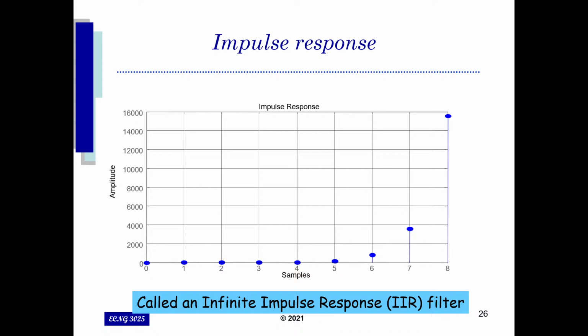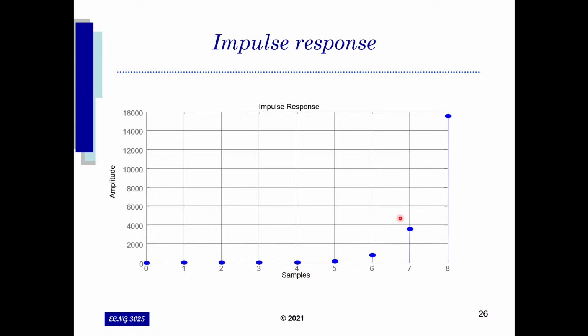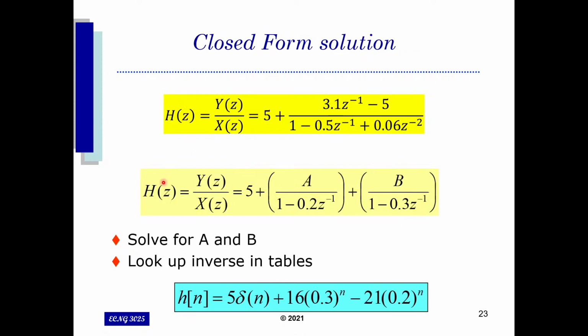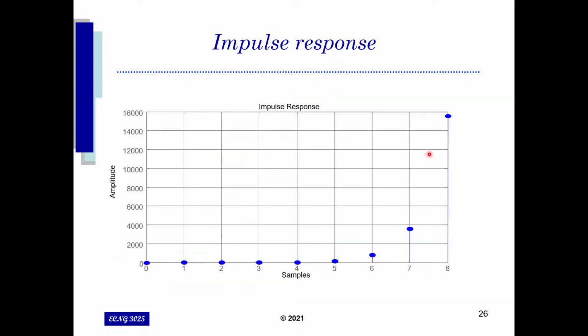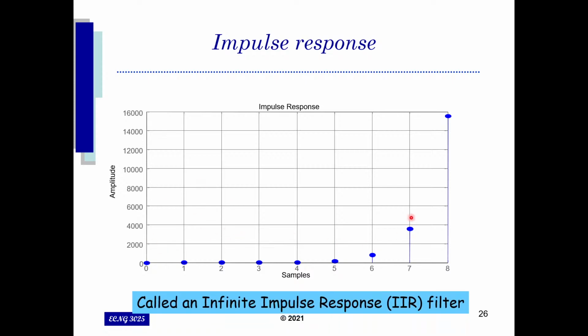The information to plot those points is basically given from the Z transform equation that you had. So we'll have the Z transform equation here, and then we substitute z equal to e to the power j capital omega, transforming this from H of z into H of omega. And then you plot for individual values of omega to get that impulse response graph. But like I said, we won't ask you to plot these graphs. This is just for evaluation purposes later on, if you're trying to do some sort of filter design and you do need to see the impulse response.